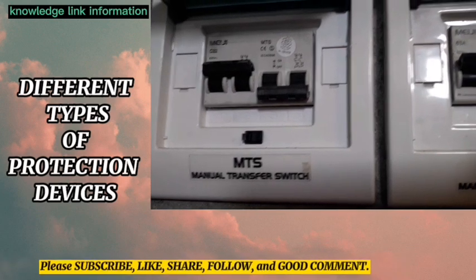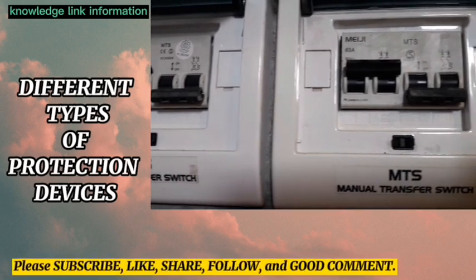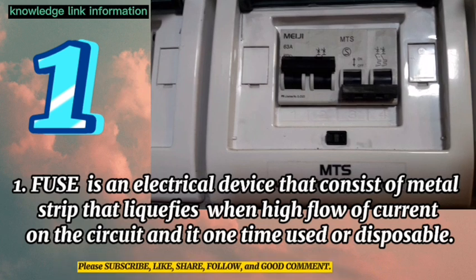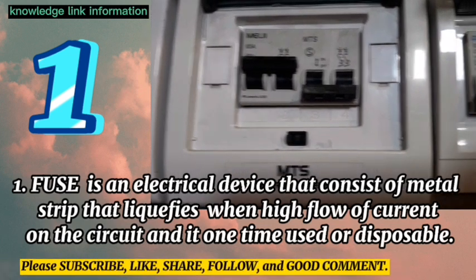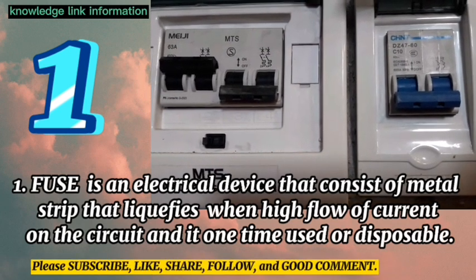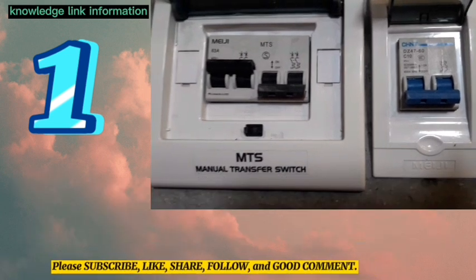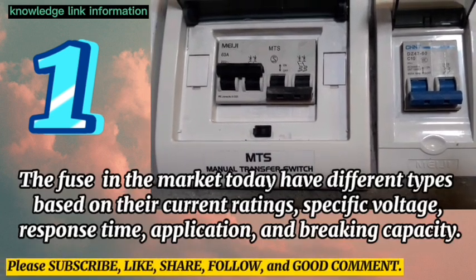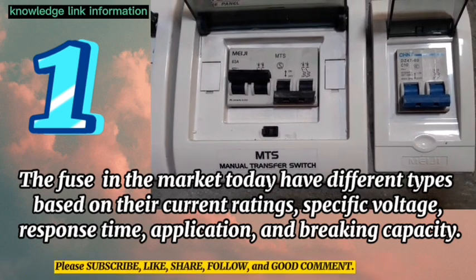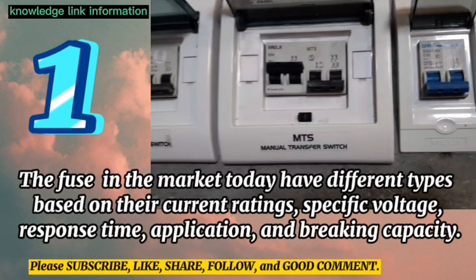Different types of protection devices. Number 1. Fuse is an electrical device that consists of metal strip that liquefies when high flow of current on the circuit, and it is one-time used or disposable. The fuse in the market today have different types based on their current ratings, specific voltage, response time, application, and breaking capacity.